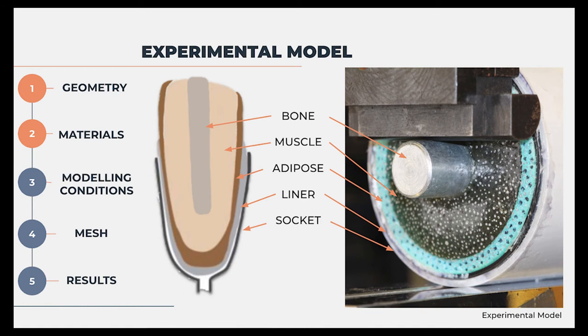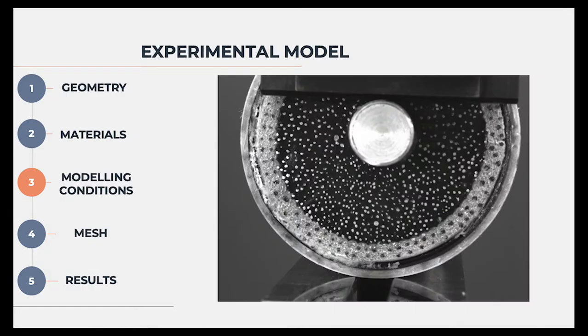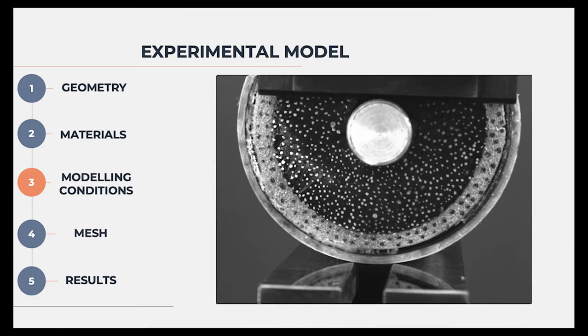The other components were modelled using gelatin, foam, rubber and PVC as previously completed in the literature. The experimental model was loaded at 2 points on either end of the steel rod, whilst being both vertically and horizontally supported on the base. Dots were randomly distributed across one face of the model, such that the model's strain could be accurately captured by digital image correlation. All of the results taken from these models were taken as a stress in the direction of loading at the outer surface of the stump.